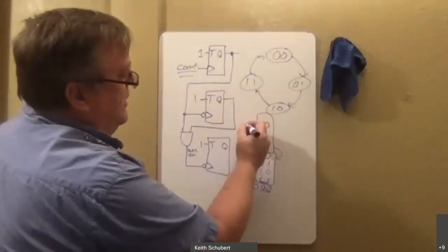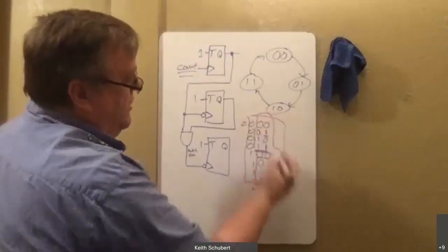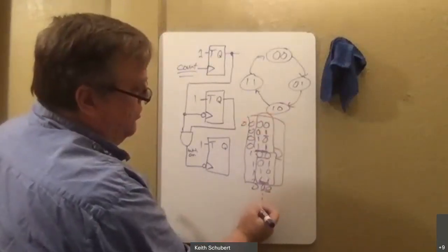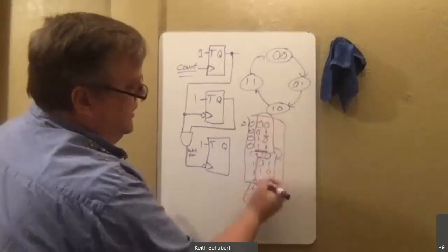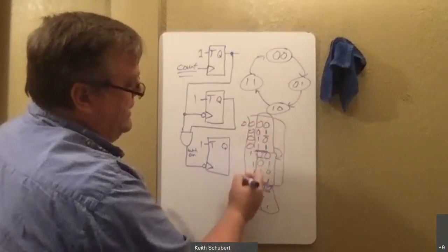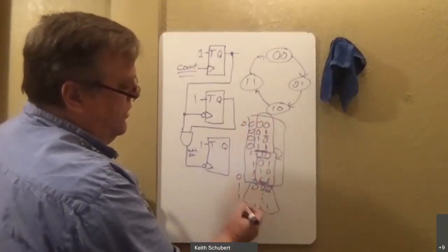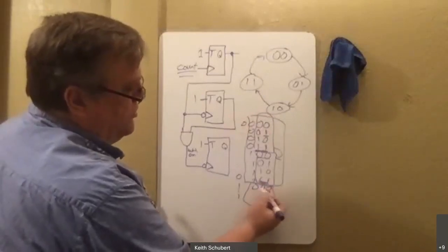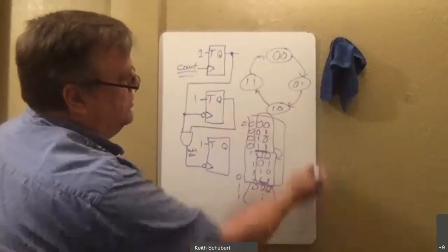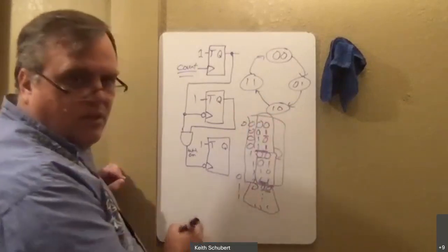You can imagine I've got a unit here. I might have another whole unit, 0, 0, 0, all the way to 1, 1, 1. Right? Doing that same internal pattern. The last bit is 0 for all these, 1 for all of these, and then it'll go back to 0. So again, when it's all 3 1s going to all 3 zeros, all 3 1s going to all 3 zeros, it toggles the next bit.